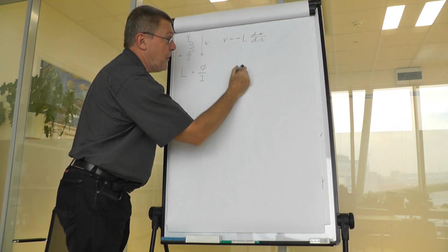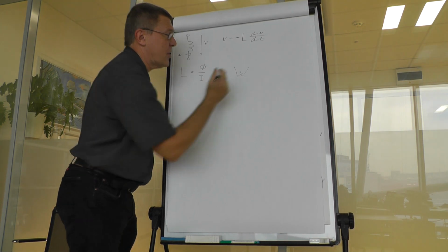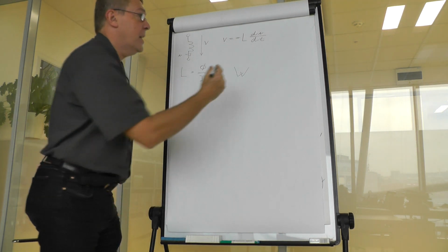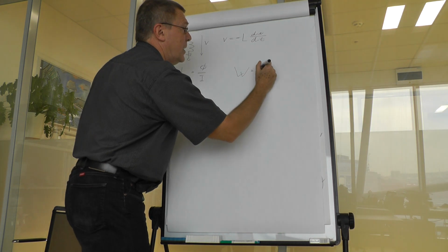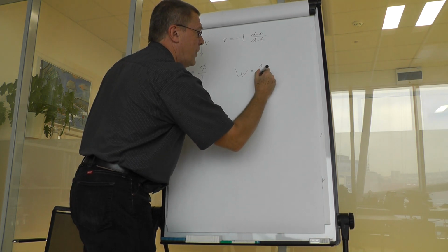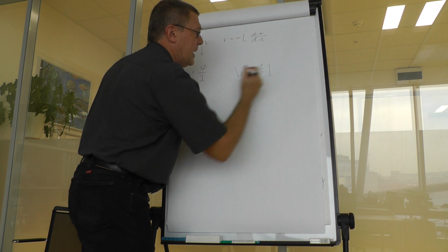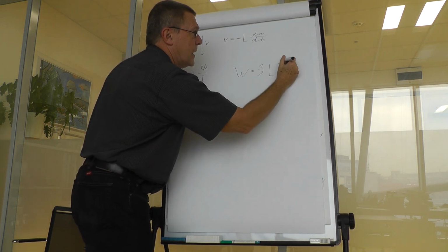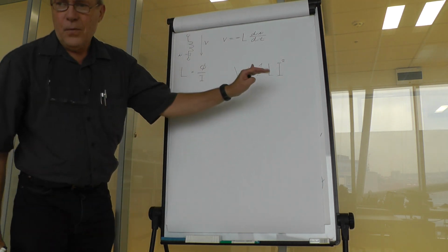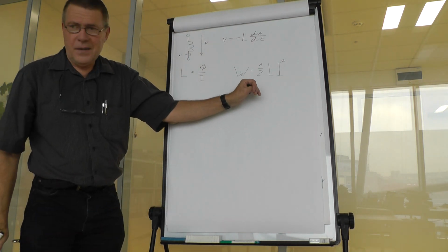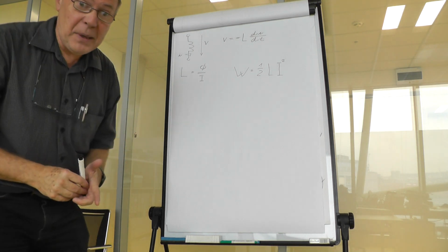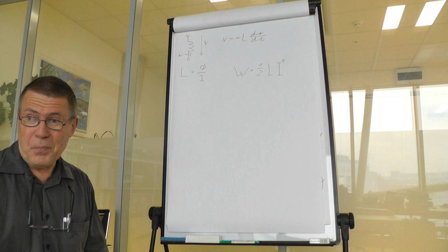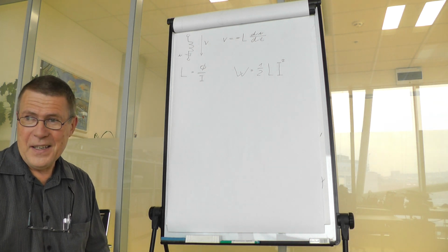This third definition says that the energy contained in the magnetic field of an inductor is equivalent to 1/2 of the product of inductance and the square of the current. Now, this is fully true for the assumptions we have made at the beginning, that we are discussing linear isotropic stationary media.